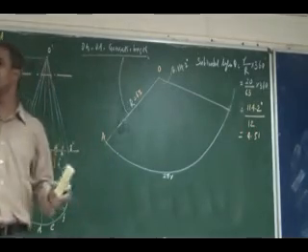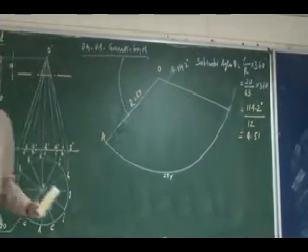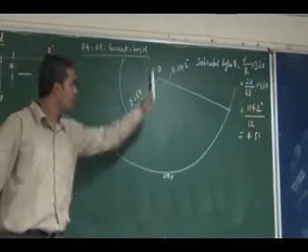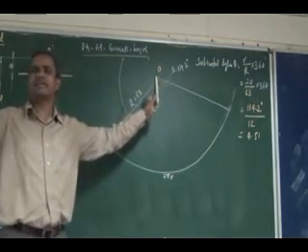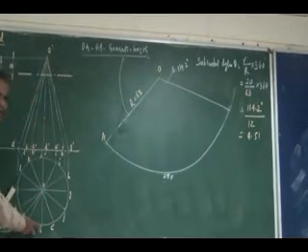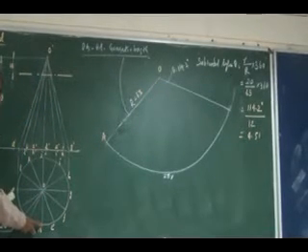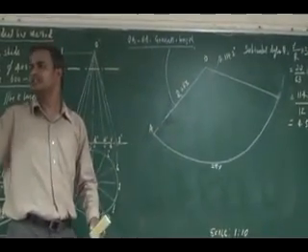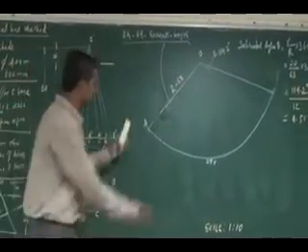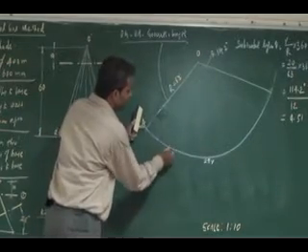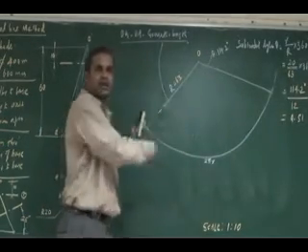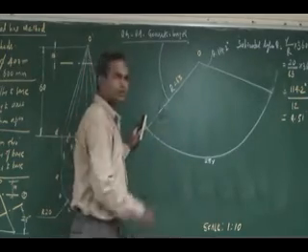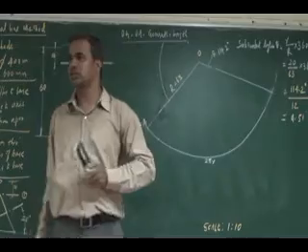So the angle you have to divide into 12 divisions. That is the correct procedure. For your easiness, to quickly do this development, you know that you have to divide that angle into 12. That is the exact procedure. Now the segment length alone you measure: the circumference length 125.6 divided by 12 is 10.4. You cut 10.4 along this circumference on your development. So you will get 12 segments. Then you show the generators, 12 generators. Make it fast.